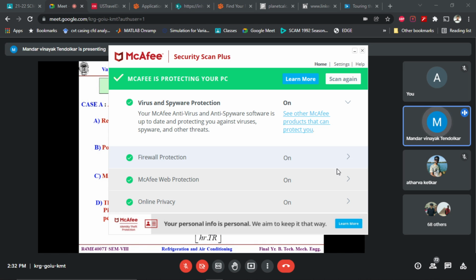So this is your mass flow rate per TR. If you substitute over here, the volume flow rate you get is also per TR. Then power consumption per ton, and the COP. So 4.056 is the answer which I have got for the dry one.